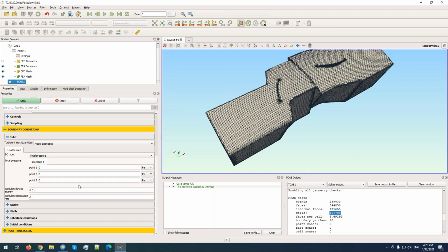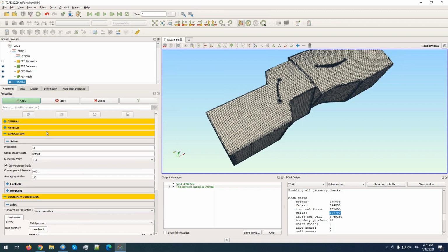So total pressure at the inlet, and we are in the incompressible mode. The solver operates in so-called kinematic pressure, so the pressure divided by the density. We can treat these values as reference values, so the relative value is 0 pascals.